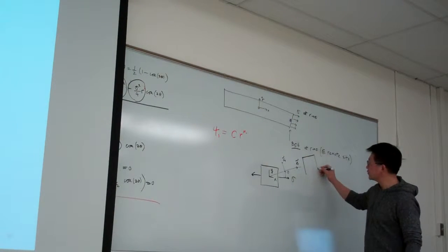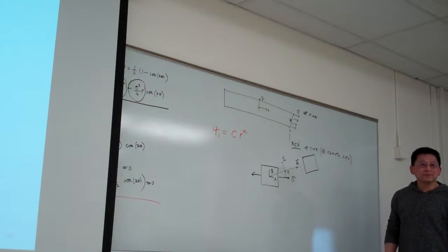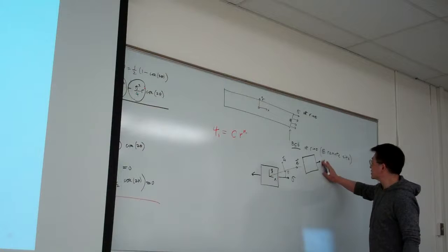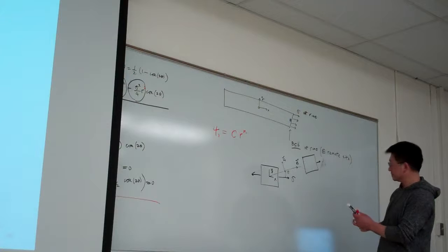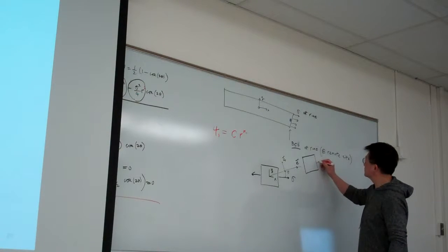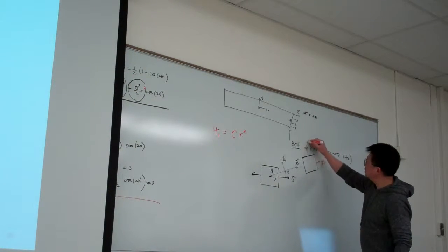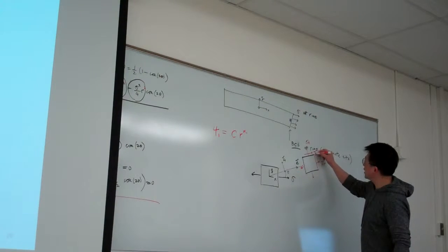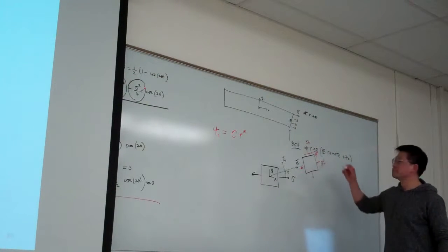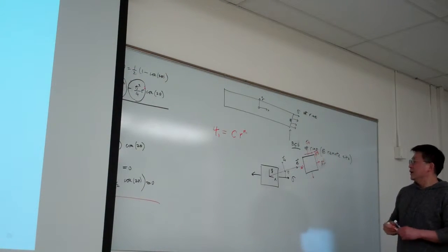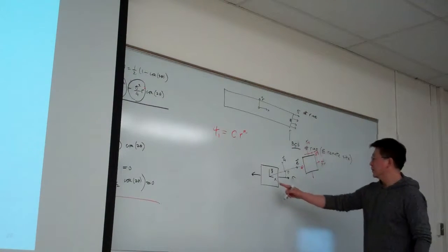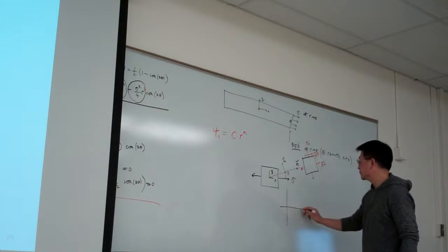This is our sigma r, and this will be sigma theta, and corresponding here will be tau r theta, something like this, right? How can we do this? For example, we can use the Mohr circle. We draw the Mohr circle for this case.